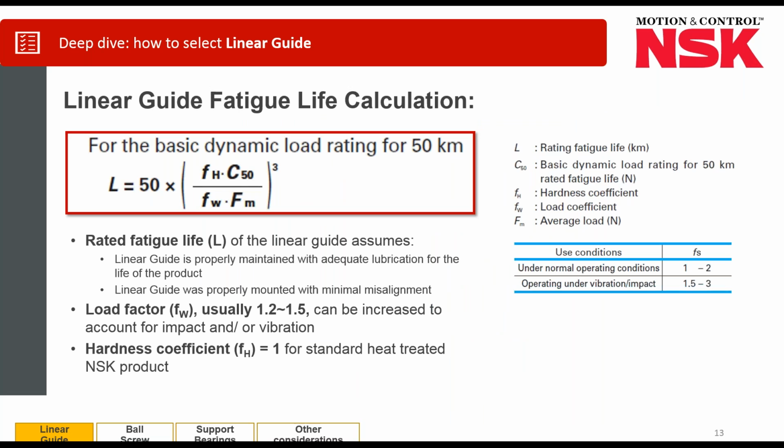So once we come up with the load, this is just the basic calculation I wanted to show you. There's a calculation for the life, which is L. And in the equation, you'll see a C50, which is the load rating of the linear guide, and an FM, which is the actual load that the linear guide sees. So it's a very basic equation: load rating of the linear guide divided by the load, cubed, times 50, and that is the life of the linear guide. Traditionally, we calculate this in kilometers of running life, so we can know how long the stage is going to last as far as distance, and then we equate that distance to the stage travel or stroke. Usually it's cyclical, like back and forth 100 millimeters, and then we can calculate how many cycles that is, and extrapolate that to how many years this particular stage can work under that load condition.